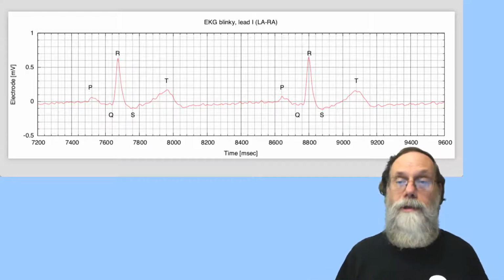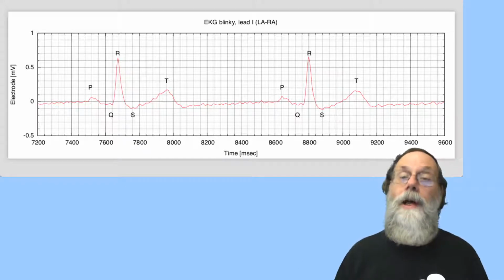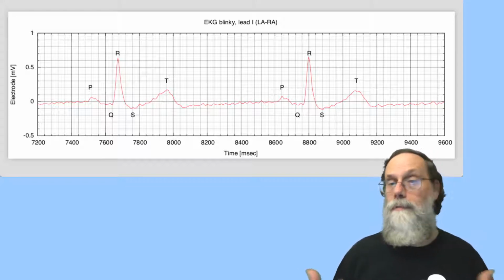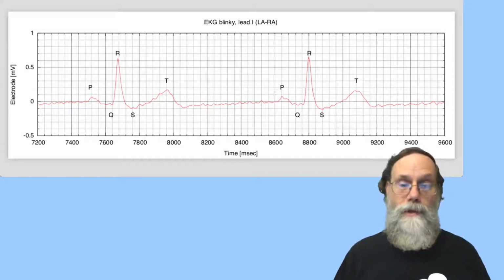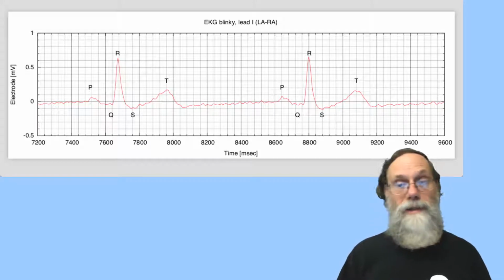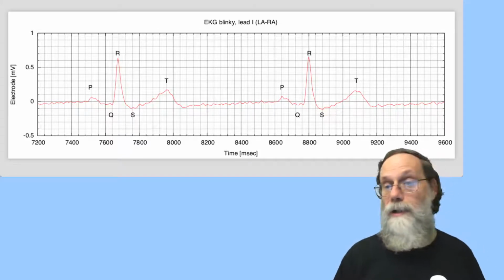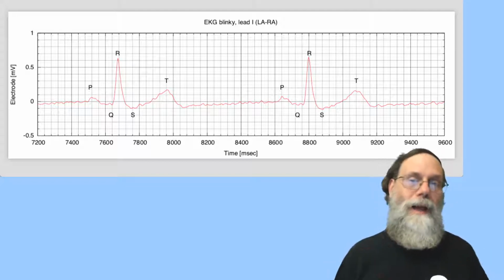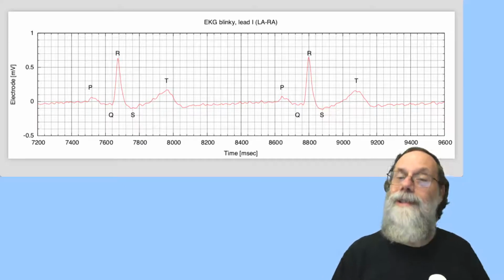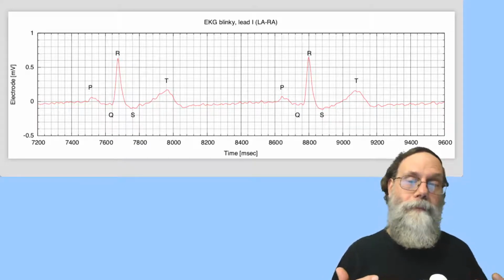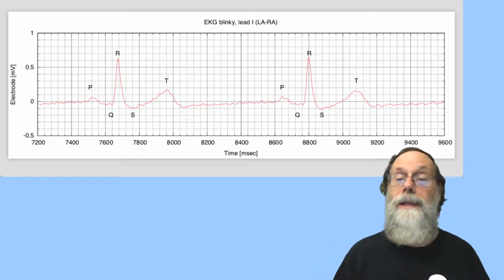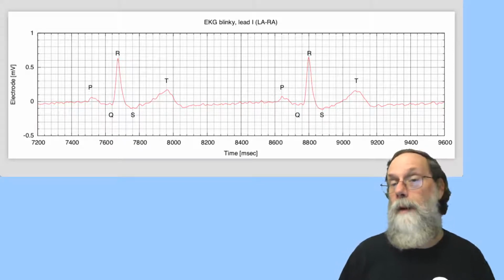The analog electronics you design have to be the matching between what comes out of your sensors and what goes into your data acquisition system. So you need to worry about things like whether this is a single-ended or differential signal. If it's a differential signal, how big is the signal? How big is the common mode? Because obviously you want to make sure that you take only the signal and not the common mode noise. And that controls things like what your first stage has to be. There may be limitations on the gain based on avoiding clipping due to common mode problems.